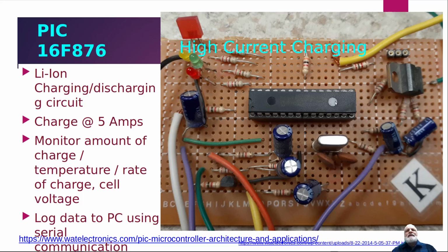plug it in. You can't actually even program them when they're in place. This was running some LEDs telling me the status of where it was at within the program. And then I just have some various different capacitors in here. This particular one, I did need to wire up a crystal here as part of the clock mechanism for the oscillator. So this is a crystal here.